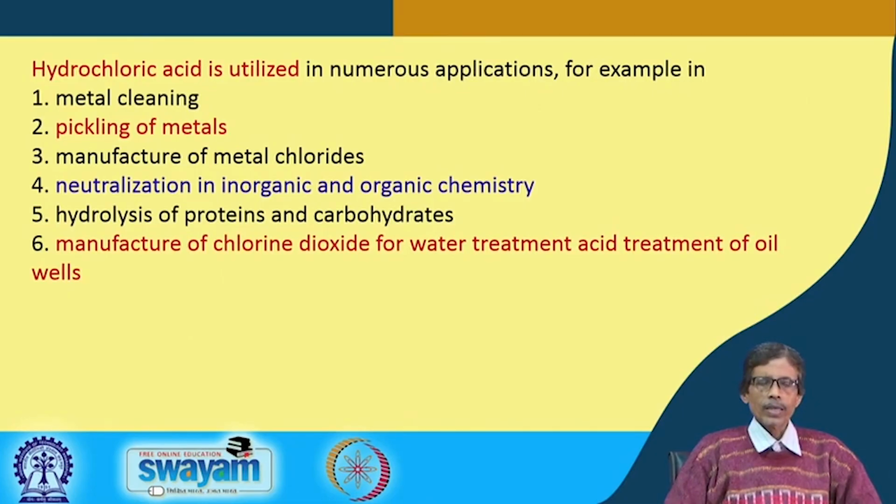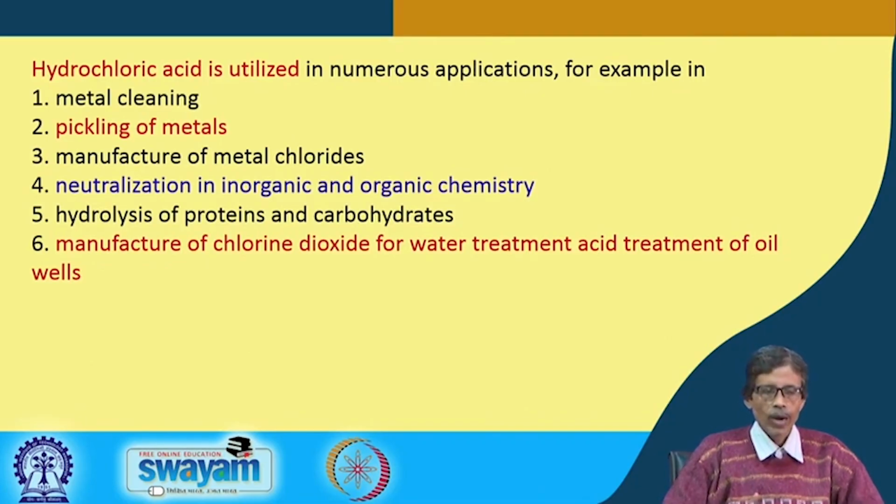When we go for the neutralization, we are taking care of the pH of the medium, but we may ignore the corresponding supply of anions from the acid we are using. When you use hydrochloric acid and add a huge excess of it to adjust and control the pH, by that time we are contaminating the reaction medium with a huge amount of chloride ions which is coming directly from the HCl.